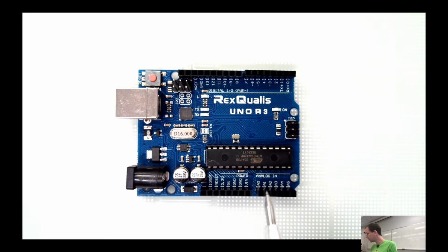In this particular case, the chip on here is called an Atmel 328, but there are literally thousands of different kinds of microcontrollers, and they vary in a lot of different ways, like how many pins they have on them so that you can control more things, the kinds of communications protocols that they have built into them, how much RAM or ROM they have, what other peripherals like analog to digital converters they have in them, whether they're fast, whether they're high power or low power, whether they're cheap, and so on and so forth.